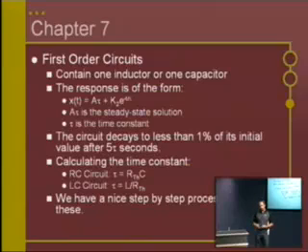We have to make sure you're thinking, okay, the steady state behavior of an inductor is to short circuit, and when it's just after a switch actuates, it acts like a current source. But when I'm doing a Thevenin resistance and I'm zeroing out a current source, that's an open circuit. Just make sure that those 3 things are very distinct in your mind, so that you don't think, well, it was acting like a current source, and so when it's not acting like a current source anymore, it acts like an open circuit.